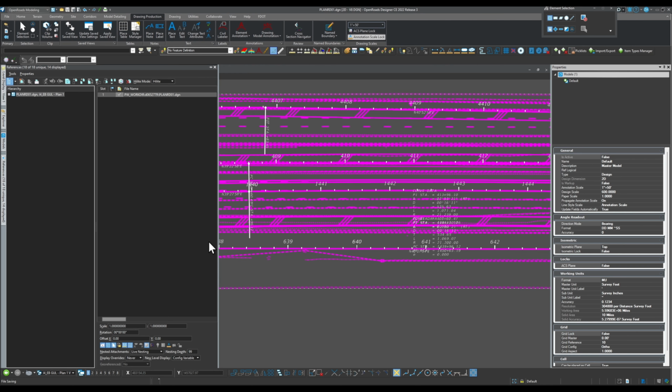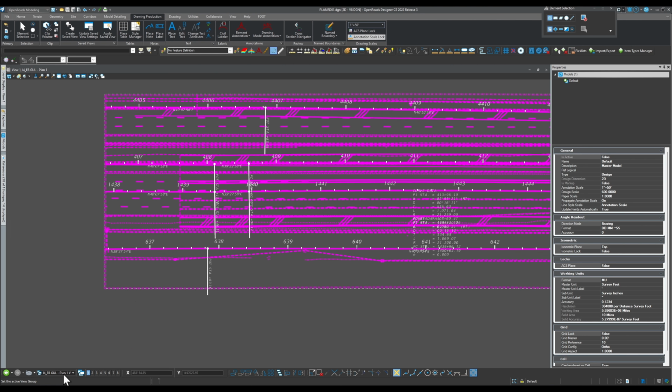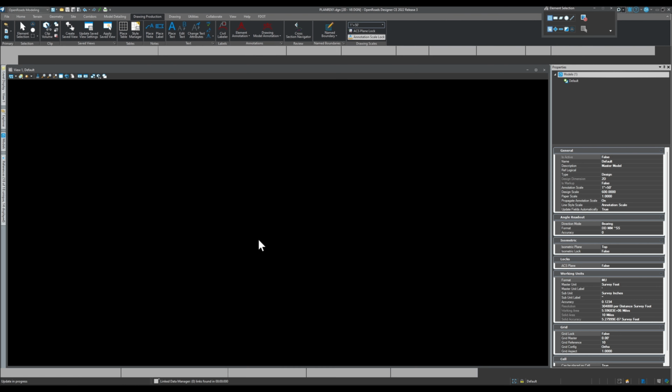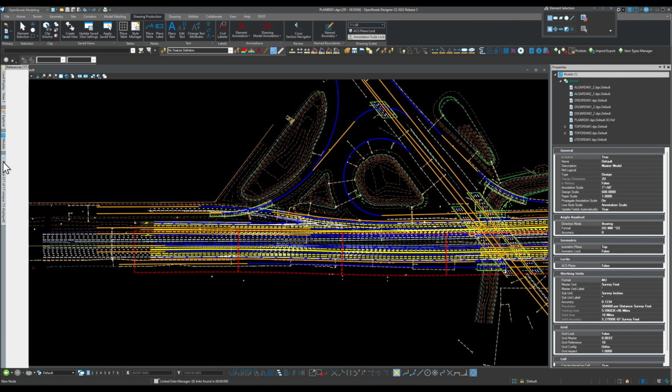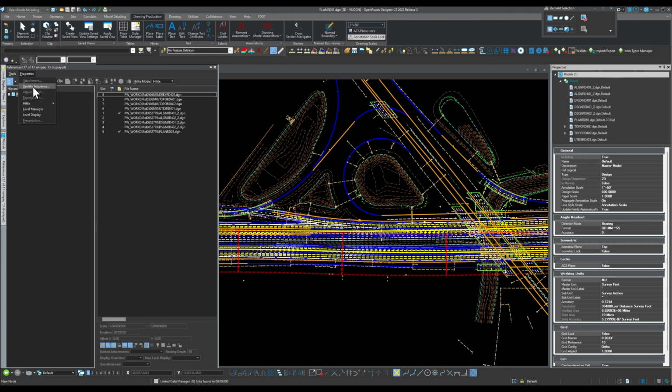But to solve this, instead of having to keep doing it one by one, the recommendation I would give you is to make a container, reference anything that you want, go to your references, update the sequence, and have that container ready. For example, Roadway has its own container, then drainage container, signing container, signal container, and then order them as you want, scale them as you want, and be done, and then just bring them here, instead of doing everything here in one place. That's also an option.